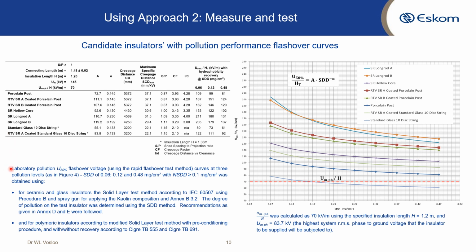We sent this lot off to a laboratory, and we specified our salt deposit densities, and we also specified our non-soluble deposit densities. We had them done for the ceramic ones in accordance with this procedure, and for the polymeric ones in accordance with that procedure, and we ended up with these pollution performance curves for the various products that have been evaluated.